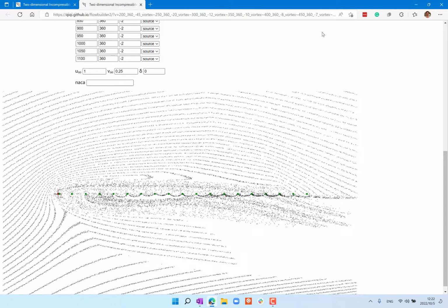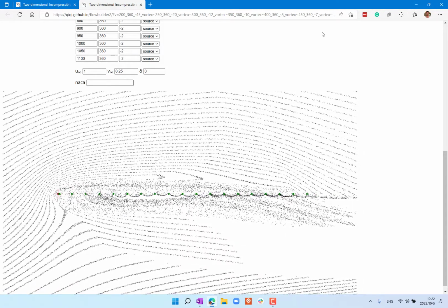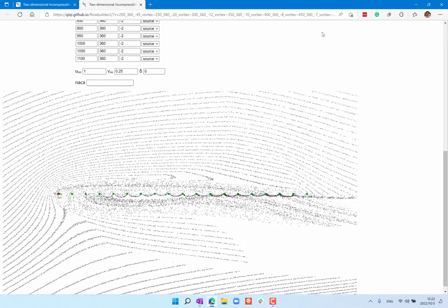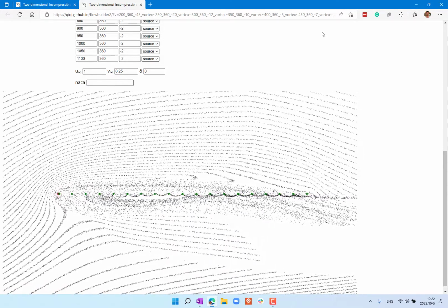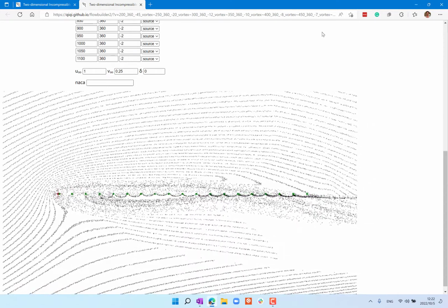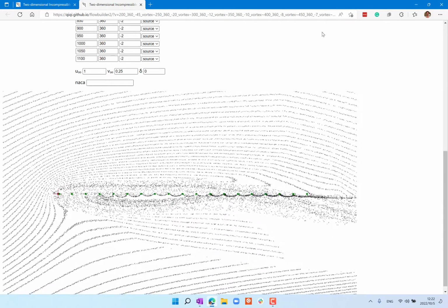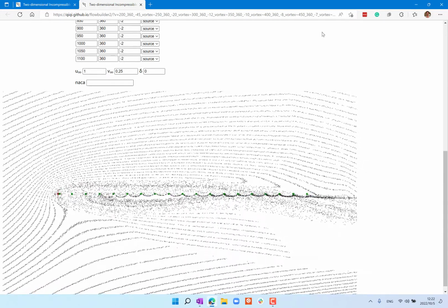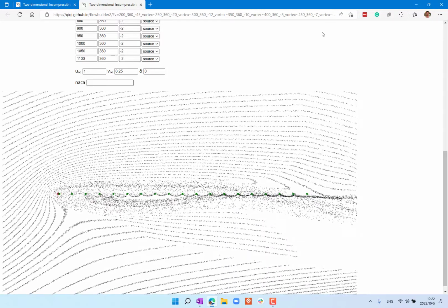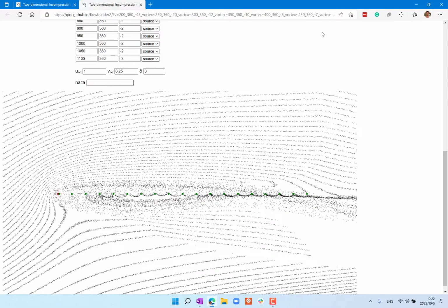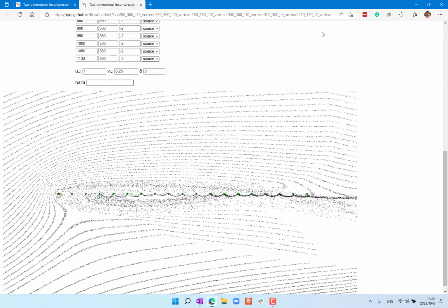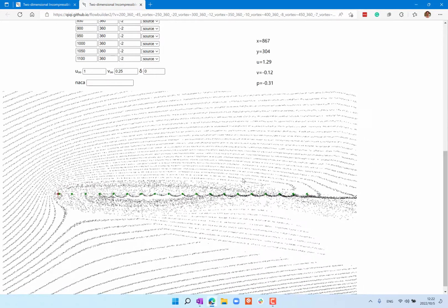Basically, the vortices determine the camber and angle of, let's forget about camber. We're going to be talking about camber next week. The vortex distribution determines the angle of attack. Okay, and if you increase the angle of attack, you just increase all the vortex strengths proportionally. And the distribution of the sources and sinks determines the thickness and thickness only. So they are independent. Okay, so this is what's universal about that function.